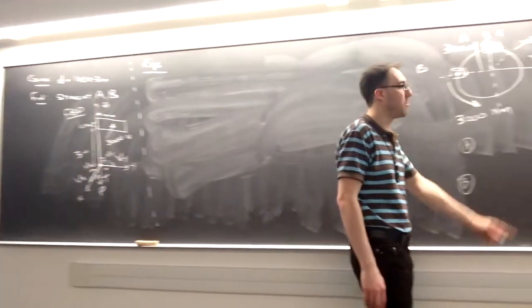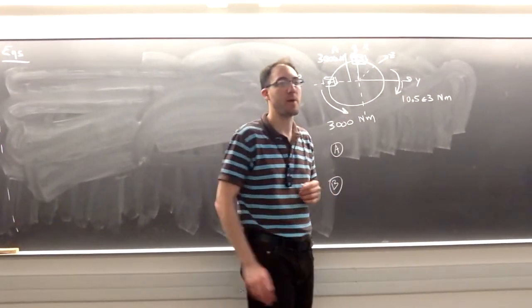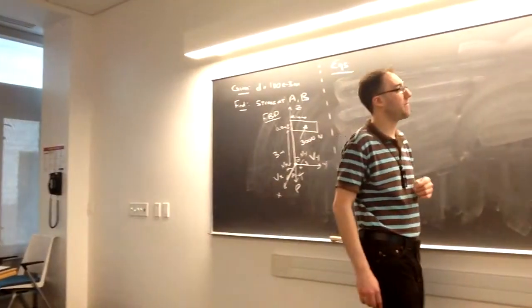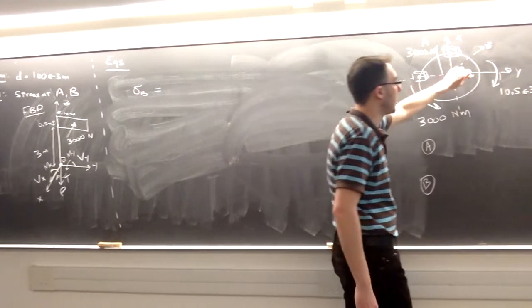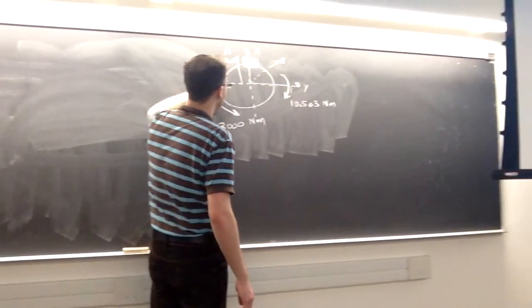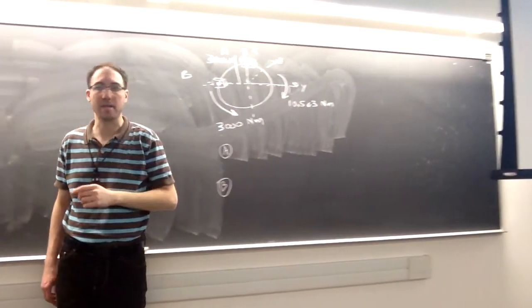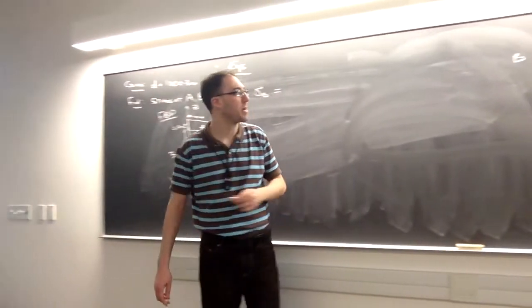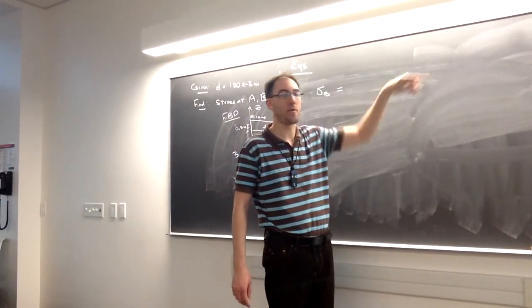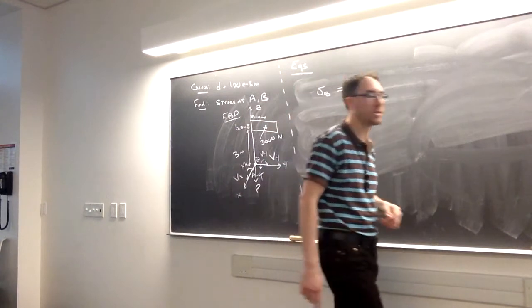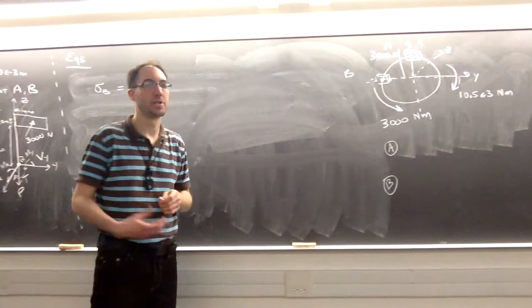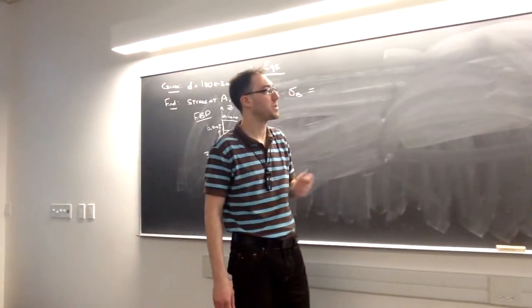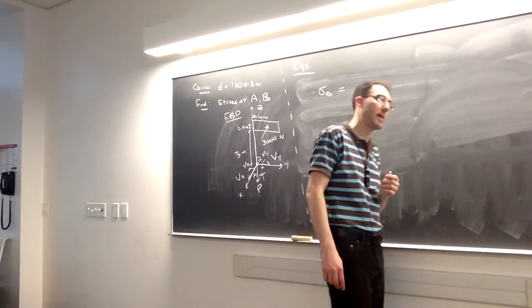We will have a bending moment caused by the moment around the y-axis. A will be affected. Will B be affected? Right. B is not because, again, from the perspective of this moment, it lies on that neutral axis. So in this case, A will be maximally affected because it's the furthest away. It's at the top relative to this horizontal neutral axis. B will not be affected. So the stress that's going to be caused at A, will this bending be tensile or compressive on point A?